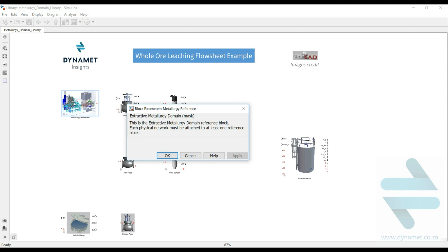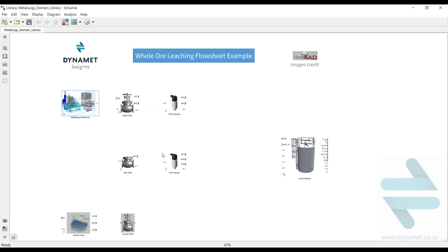This block defines our flowsheet model variable parameter space. For the sake of this video, we only have a single atmospheric leaching tank that overflows to an infinite volume reservoir called an infinite sump block. We then also have an atmospheric feed block for the gas, because air may need to flow into the tank, for example, if there's a sudden drop in a tank level. This is just one simple example of the physical reality included in our models.